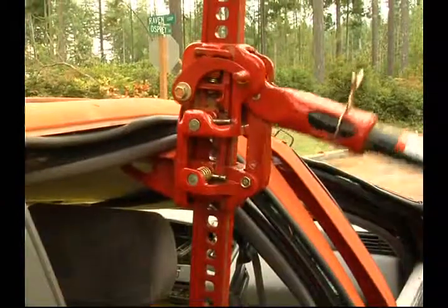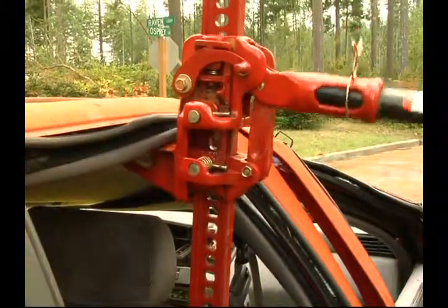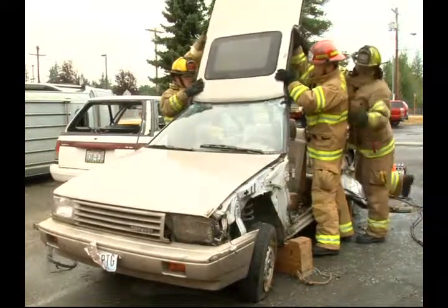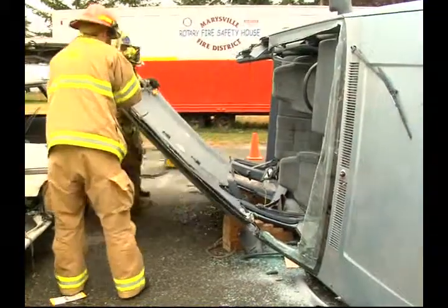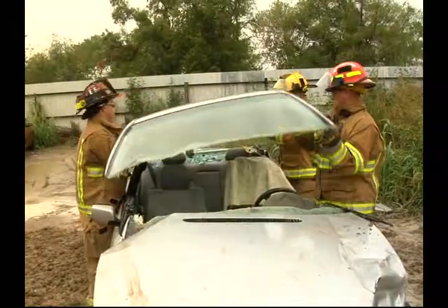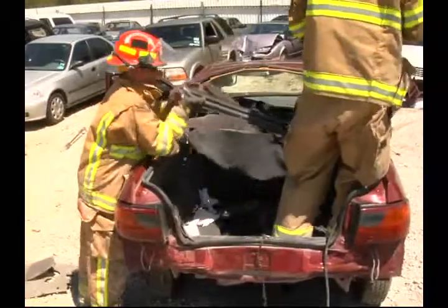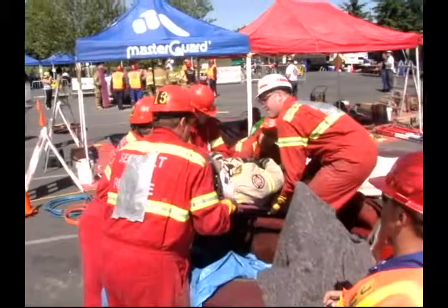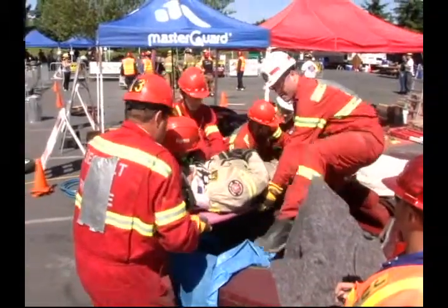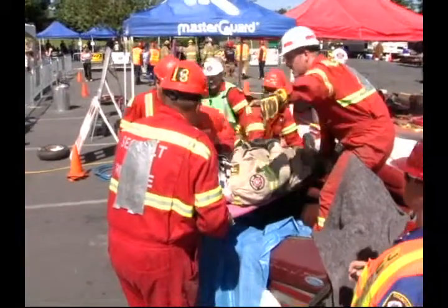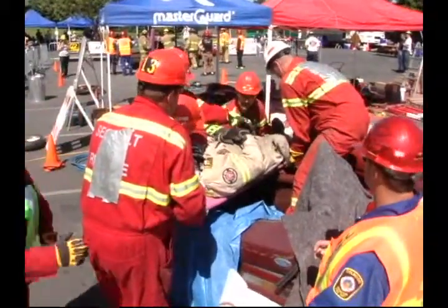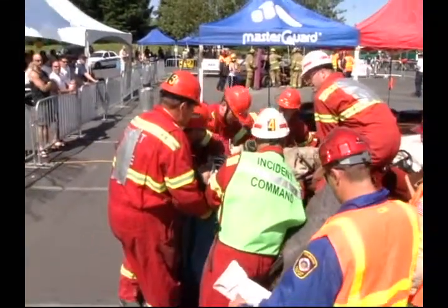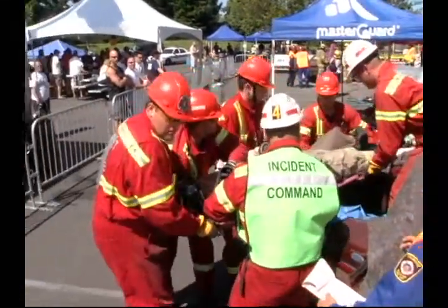In this program, you have seen how to perform procedures on a collapsed roof, how to perform a roof flap, how to lay down a roof, how to totally remove a roof, and how to perform trunk tunneling. Removing a vehicle's entire roof or tunneling through a trunk during a rescue may seem extreme, but when it enables you to gain access to a patient that needs immediate life-saving care, you quickly see how valuable these skills are for your success.